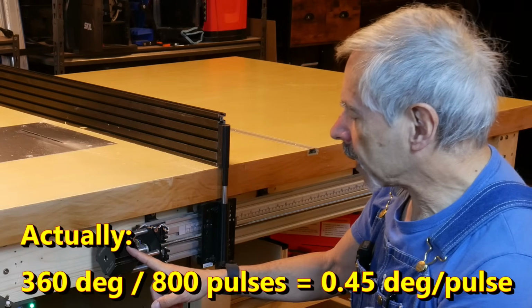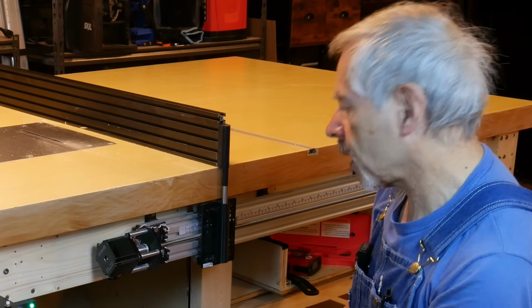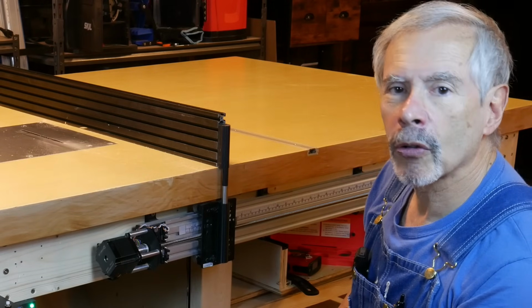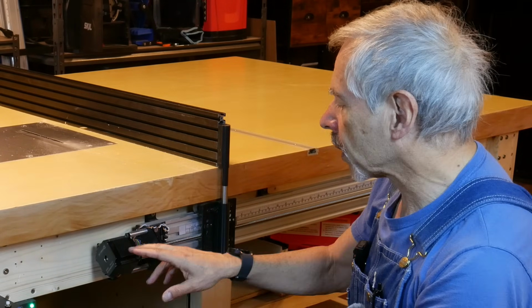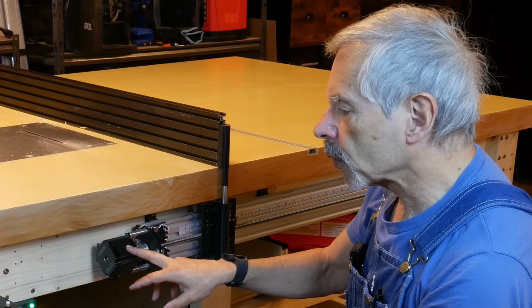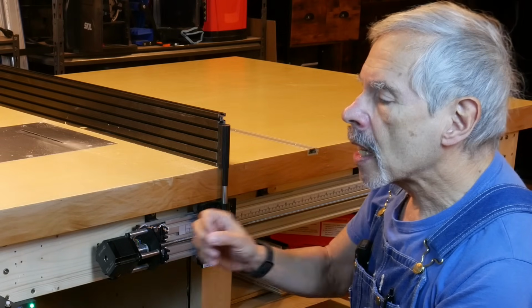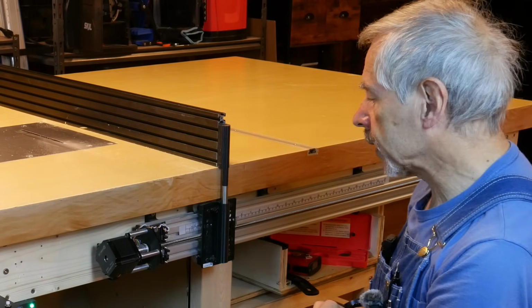If I want the stepper motor to rotate and rotate fast, I have to send it a truckload of pulses every second, 1,000 pulses maybe per second, or more than 1,000 pulses. And to do that accurately, you need a faster microprocessor such as the Teensy.